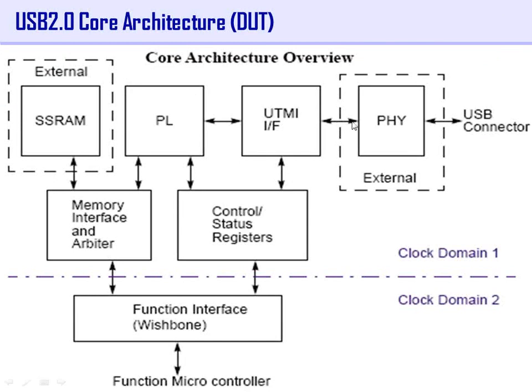It is not D plus D minus. It is converted into 8-bit data and 16-bit data format. So here there will be a clock. At this UTMI interface, a clock is required. Who will generate that clock, the outside world or the PHY? In this case, the PHY itself will generate it and give it to the UTMI interface. Any doubts on this one?